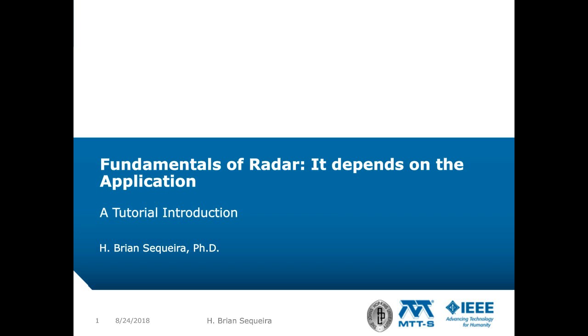Multistatic radars have separate antennas for transmission and reception. In this case, antenna separation is often sufficient that full duplex operation is possible and may in fact be critical for prosecution of the radar's primary functions. Of these, the bistatic radar is an important special case in its own right, and because many of the relationships developed for the bistatic case reduce to the monostatic case in the limit when the two antennas coincide.